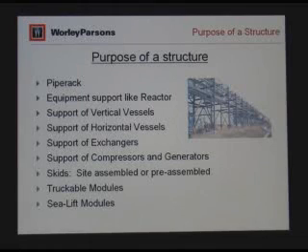So with that, we get into, again, an overview of basically, in this case, the purpose of our structures. We basically provide structures to support the process equipment. You've had presentations before, and of course the process people know that there's basically 4 or 5 basic elements that we always see: vertical vessels, reactors, horizontal vessels, pumps and generators, and a lot of piping. So for our group, the purpose of a structure is to support piping.